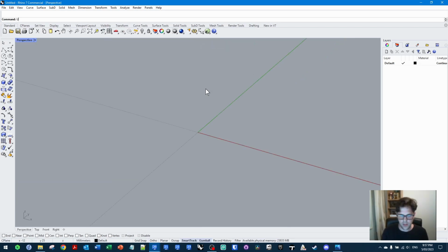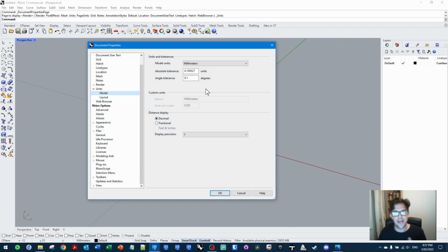It's worth noting that usually you're going to want your units to match Revit ideally. Currently we're in millimeters. So we have to keep that in mind whenever we're specifying a number, such as a value that you might want to put in meters, especially when we're doing things like divisions of grids, because we can end up actually crashing Rhino if we're not careful, if we put in a number that's actually 1,000 times smaller than what we're meant to be doing.